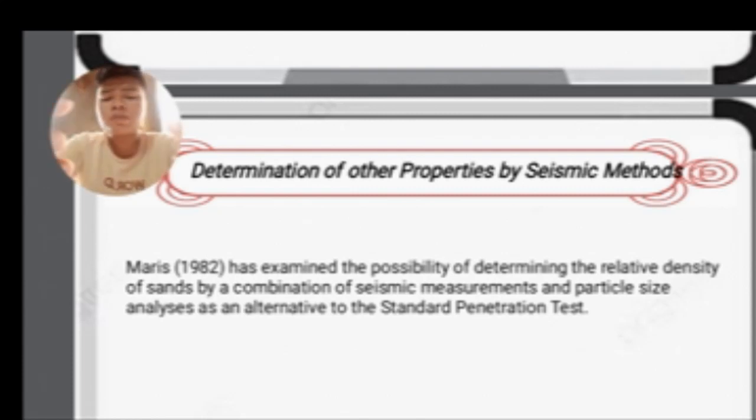So velocity measurements on uniform rock materials give the opportunity to assess changes in material properties such as density, porosity, strength, etc., which might occur as the result of weathering or alteration. So while there is a very general relationship between these parameters and velocities for all rocks, velocity measurements are only useful as an alternative to other tests when dealing with a single rock type.